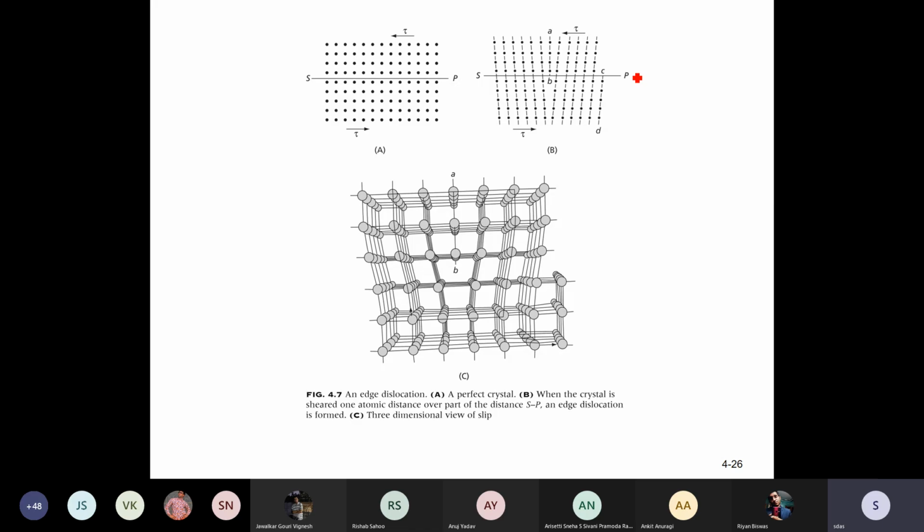And you see, when I talked about crystallography, the stacking sequence of the 0001 plane in HCP is AB, AB, AB, AB. Similarly, the stacking sequence of the 111 plane is ABC, ABC, ABC in face-centered cubic. And the atomic density, the arrangement of atoms on those planes, for those two crystal structures is identical. Slip takes place on those highest atomic density planes and in the close pack direction. The close pack direction in HCP will be the 11-20 direction, and in face-centered cubic it will be the 110 direction.